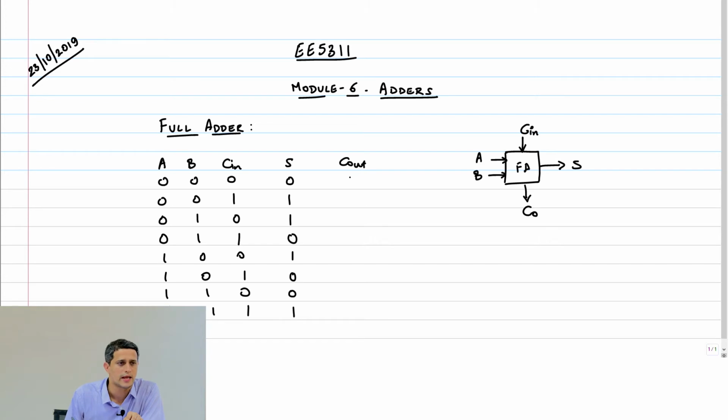Essentially the carry out is you're adding the two numbers. If you have 1 and 1, right? If you have 2 or more ones, then your carry out, you have to take it to the next bit, right? That's just like you do in decimal numbers. Only if the number goes beyond 9, you do it there. Here you do it if the number goes beyond 1. So therefore this will be 0, 0, 0. There are 2 ones here. You get 1. Again 0, 1, 1 and 1.